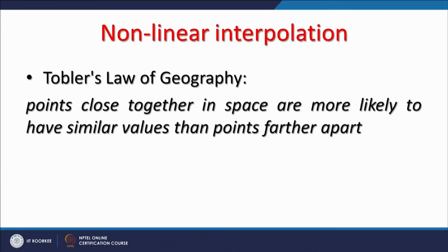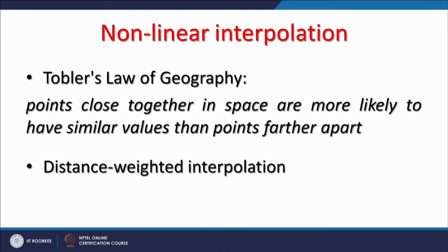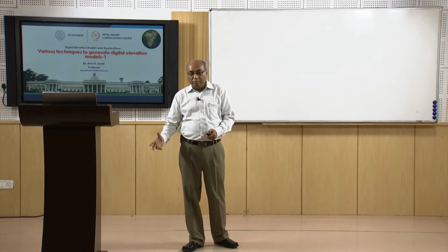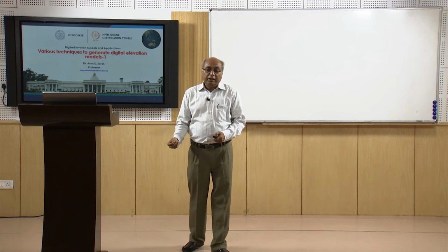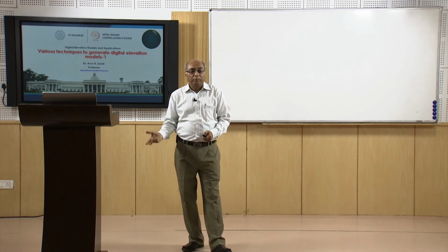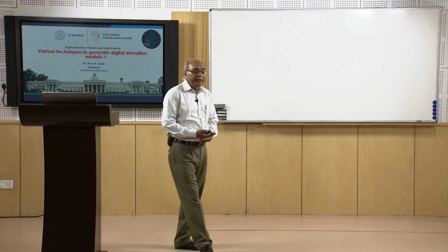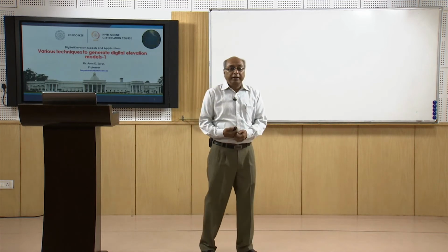Points close together in space are more likely to have similar values than points farther apart, and we can also involve a technique which is called distance weighted interpolator or inverse distance. So, the closer point will have more influence on the estimation, and points which are very far will have less influence. One very popular nonlinear interpolation technique is called inverse distance